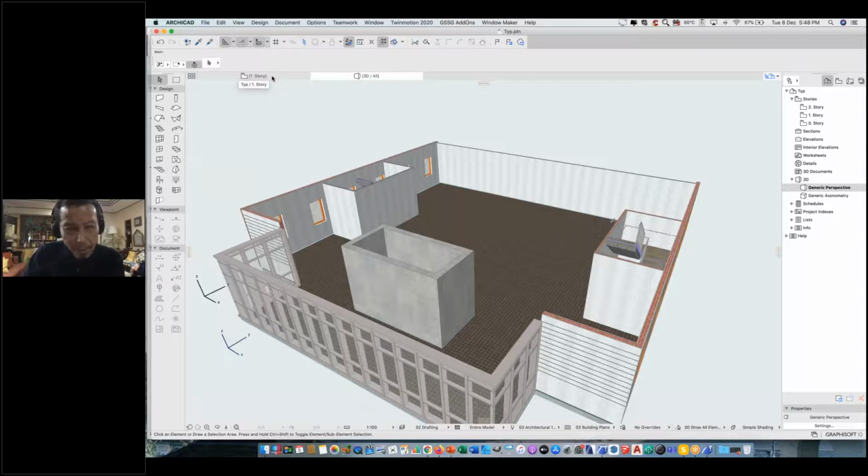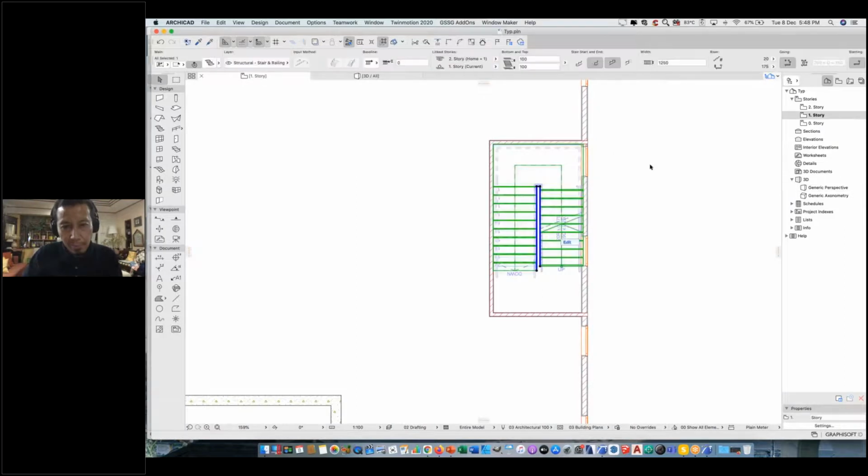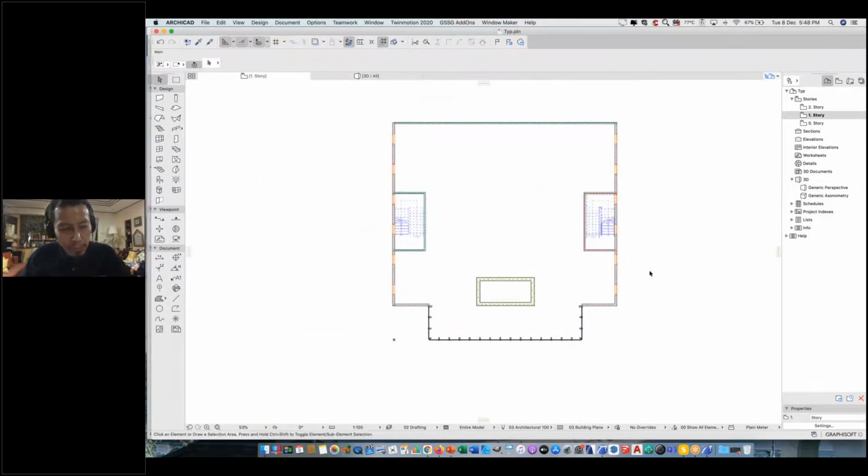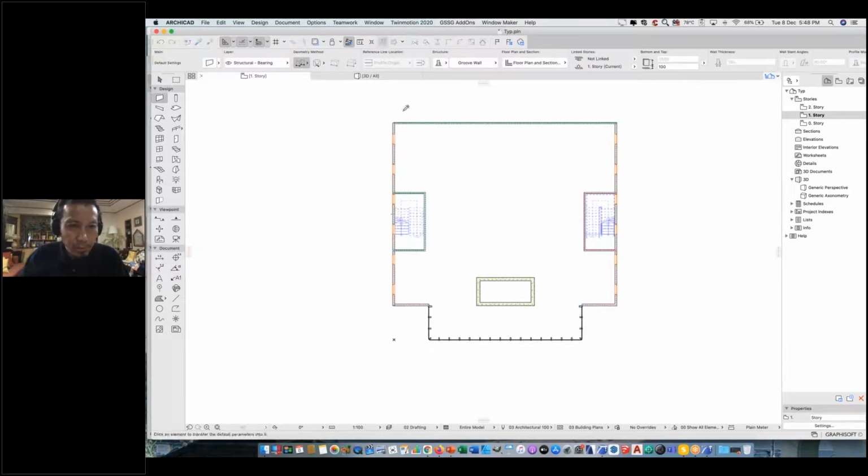Ricky is talking also about some of the methods for generating the module files. One way is to have the repository method, where you can have multiple module files that are published out from one single file. So if you have a building that has many different unit types, you can do one on each floor, and then you just use that to publish one by one. Good suggestion, Ricky. Thank you.